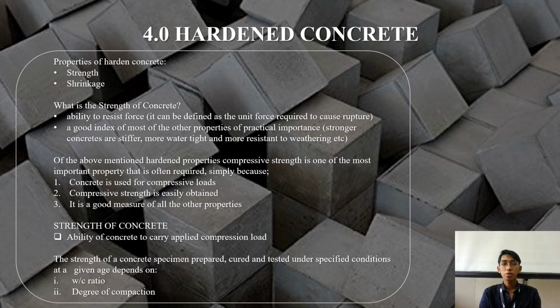With regard to concrete for structural purposes, it can be defined as a unit force referred to the core structure. Strength is a good index for most other properties of particular importance. Stronger concrete is stiffer, more watertight, and more resistant to weathering. Of the above mentioned hardened properties, compressive strength is one of the most important properties that is often recommended, because concrete is used for compressive loads. Compressive strength is easily obtained, and it is a good measure of all the other properties.